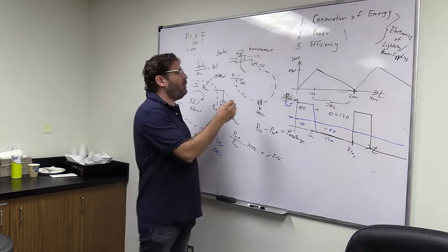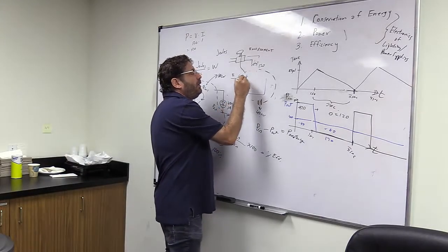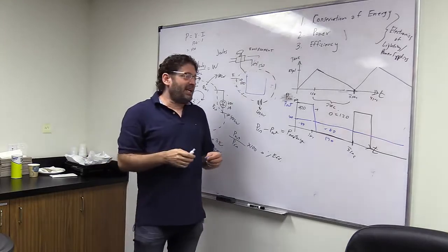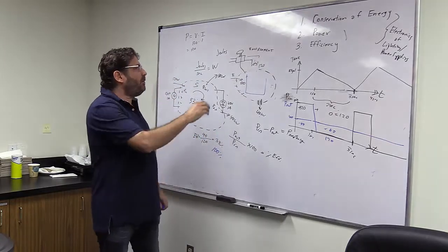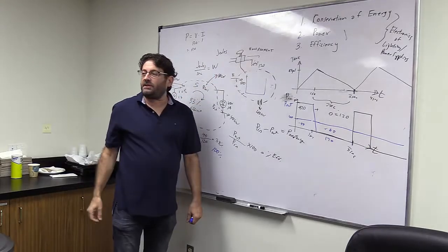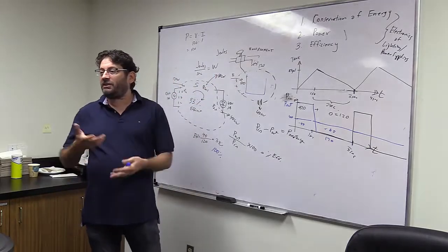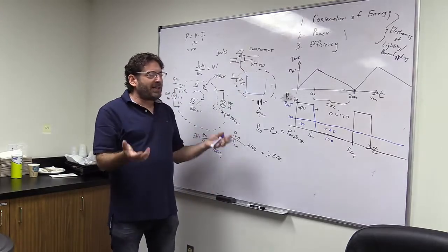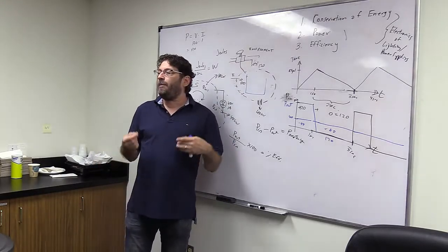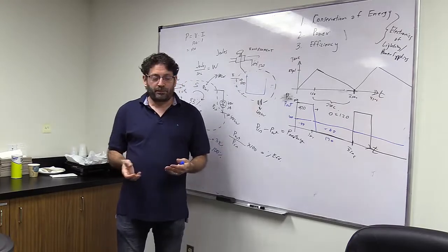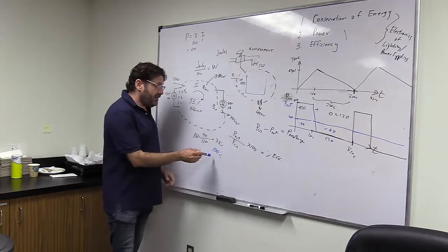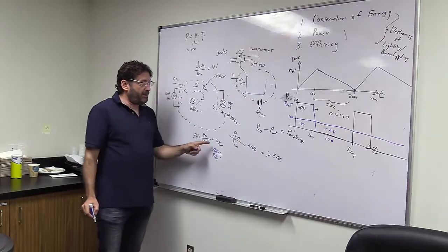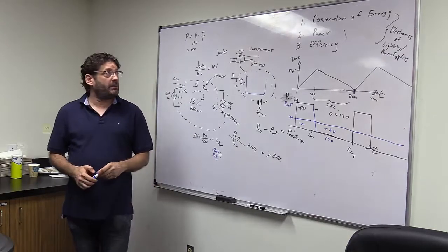Now you might say, well, I could put the gauge a little before the top so that it makes up for that. And there's lots of tricks like that. But also, the piping has some resistance, right? So it takes some energy away from what's coming in when you put it in. There's a lot of practical reasons why you can't get it to 100%. But even if you get 90%, it's still a lot better than 33%, okay?